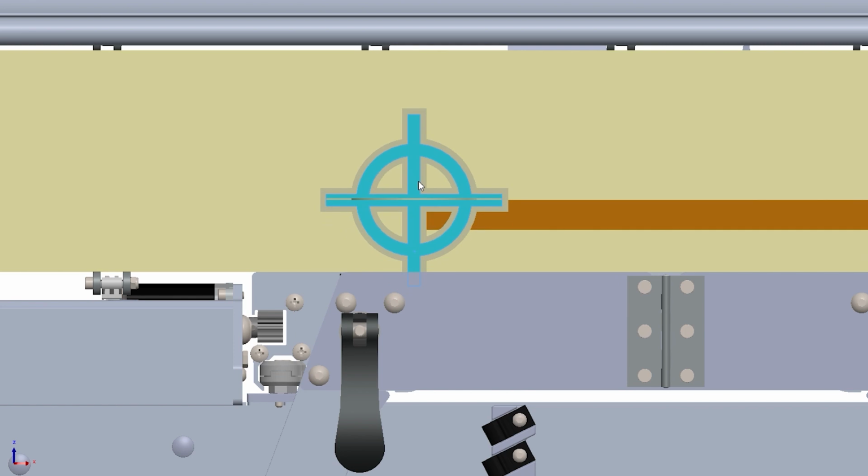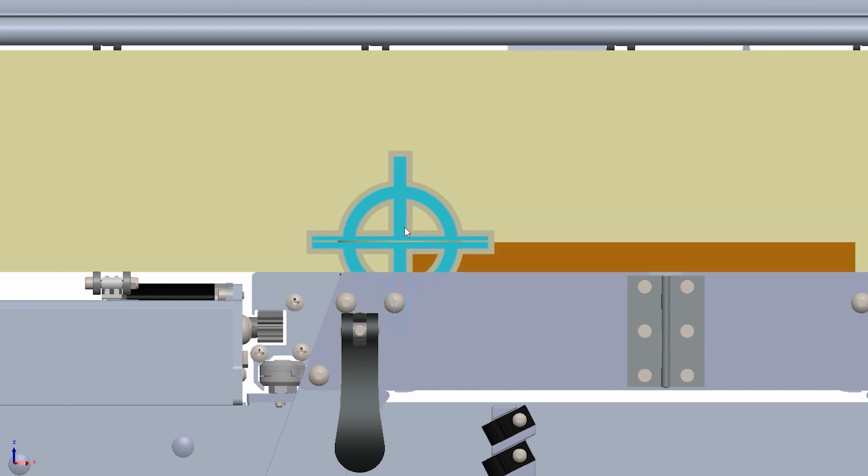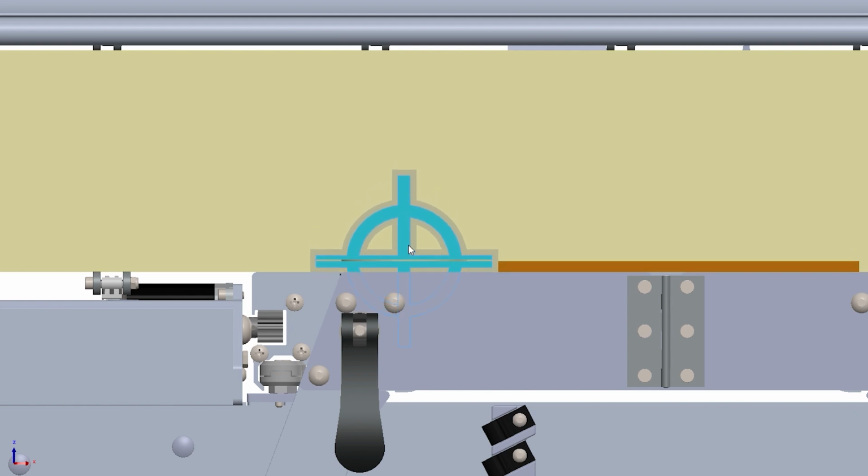Now I can position my job file to be high enough to include the thickness of a spoil board, or put the job file directly on the machine bed. But again, being careful not to position my working datum such that the job file would cut outside SmartBench's workspace.